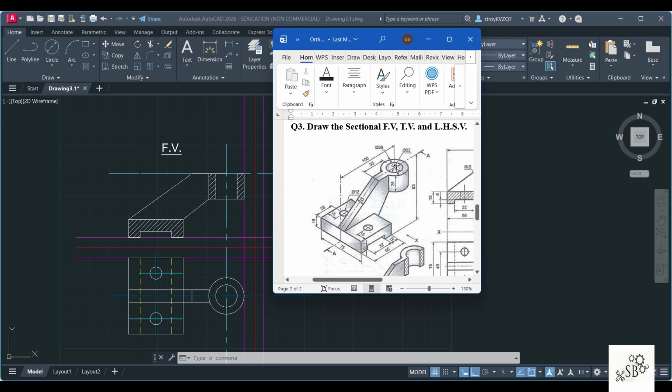So the outer diameter is going to be 36. This height will be 25. This inner circle you cannot see from the side, hence it will be dotted. Then you have this straight rib which is running right from here up to this height. And then here you are going to draw this box whose height is 18 and this length is 75.